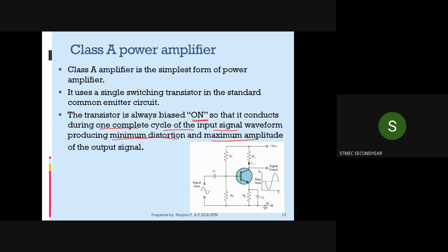And here, actually, this is the difference, this load resistance. This will be a very low value. Also this transistor will not be our normal BJT, that is normal BC107, it will be a power transistor. That is the only difference. So circuit arrangement will be same as our voltage amplifier.